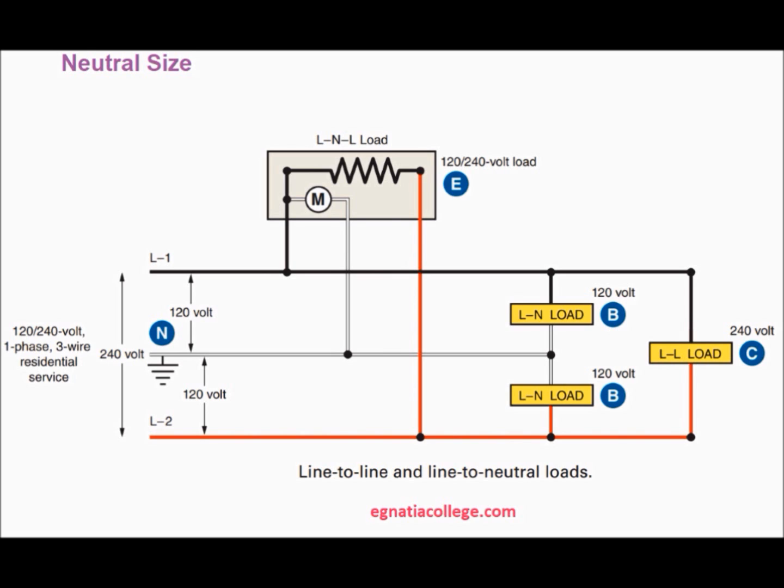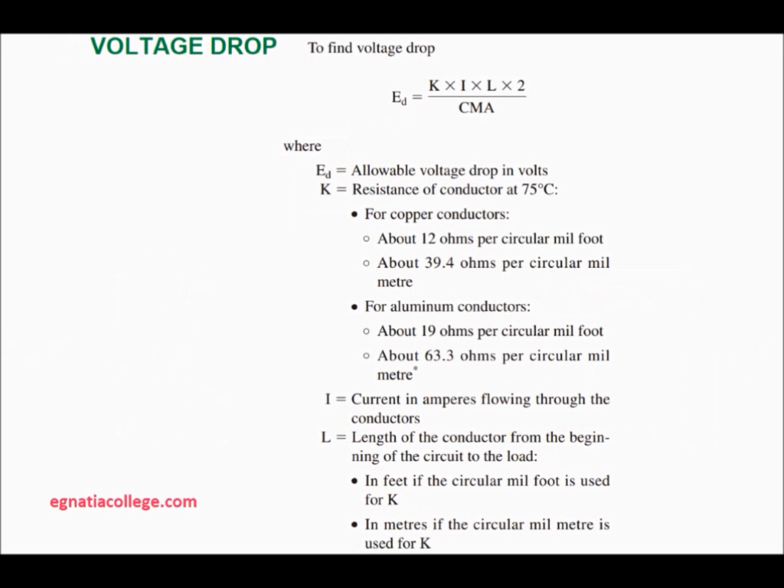Voltage drop. Low voltage can cause lights to dim, television pictures to shrink, motors to run hot, electric heaters to produce less than their rated heat output, and appliances to operate improperly. Low voltage in a home can be caused by wire that is too small for the load being served, a circuit that is too long, poor connections at the terminals, and conductors operating at high temperatures having higher resistance than when operating at lower temperatures.